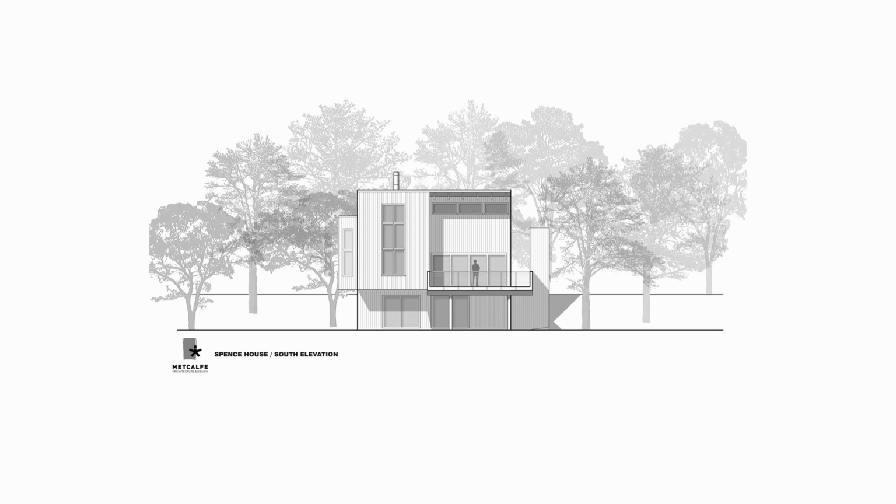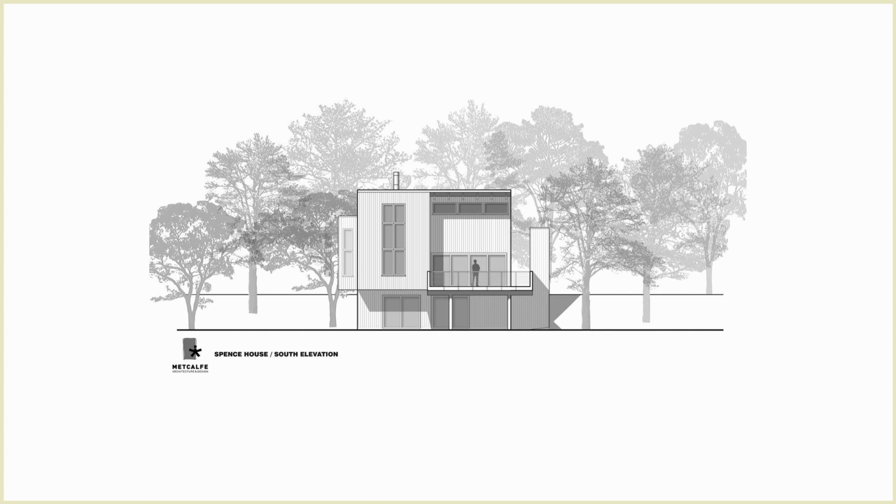So if we look at this particular drawing, you can again see the things that are thickest are coming out in front. And it's kind of an interesting holdover. We talk a lot in the graphic design portion about hierarchy. Same thing happens in architectural drawings. We want a hierarchy of these line weights. So the thickest line is right here. That's line 1. Next thickest line is this balcony right here that's coming out towards us. That would be line thickness 2.